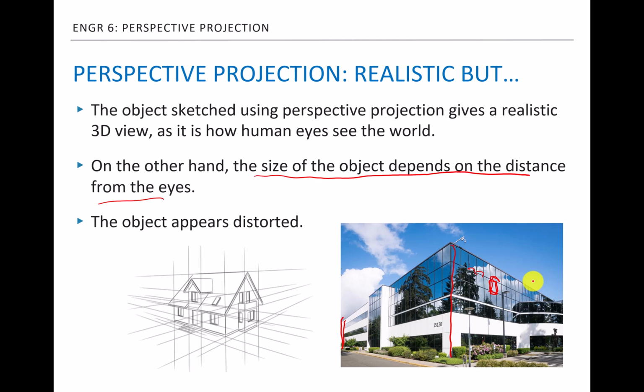So it is very difficult to know, measuring from this picture, what each object's distance or length is. So this kind of projection is not appropriate for manufacturing purposes in mechanical engineering. So perspective projection is not really used in mechanical engineering, but it is used a lot in other industries, like, for instance, interior design.